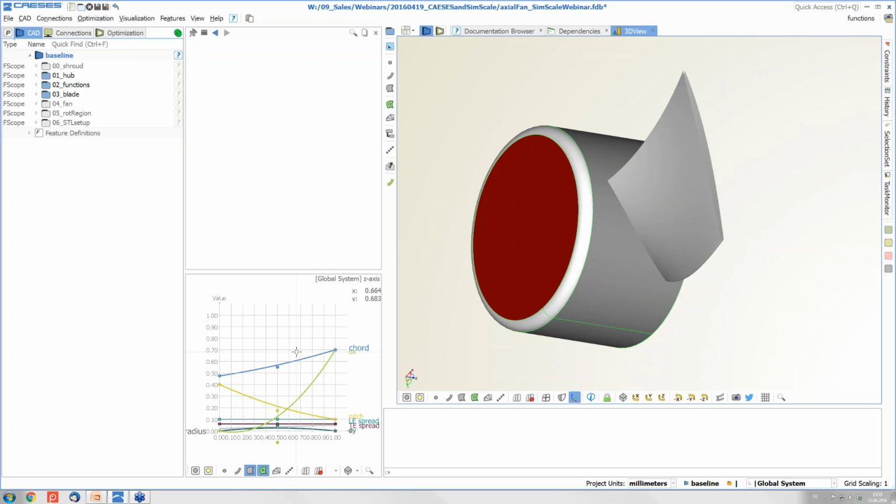airfoil theory. So if we want to increase the flow that is induced by the fan, basically we would like the fan blades to create more lift. So the two things that easily come to mind are we can increase the angle of attack of the profiles.